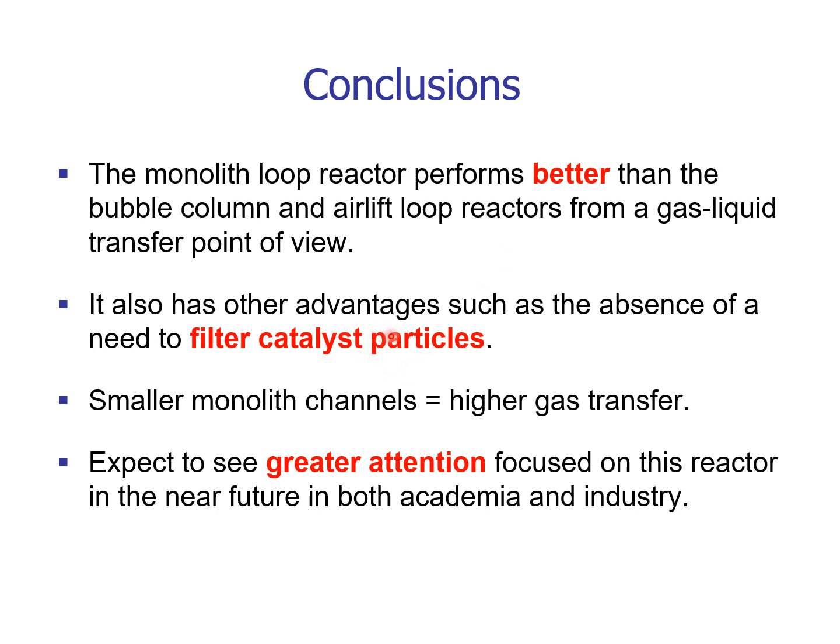It also has other advantages in relation to bubble column slurry reactors, because there's no need to filter the catalyst particles, because the catalyst is introduced as a thin layer coated on the inner surface of the single channel within the monolith construction.